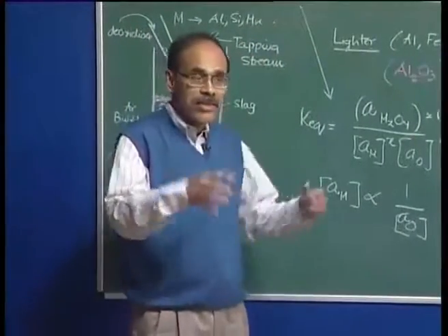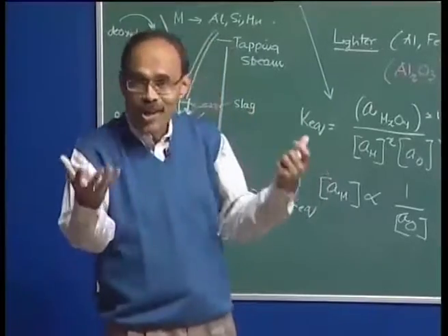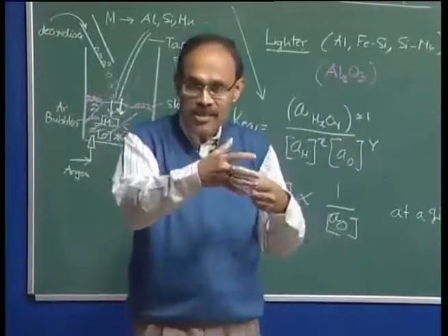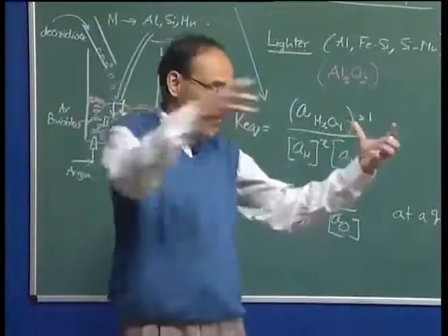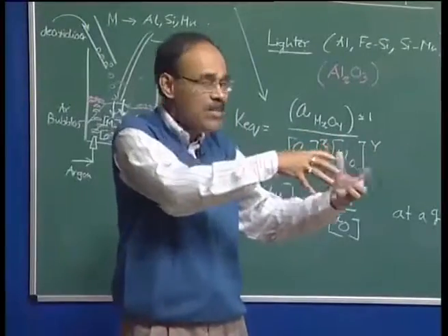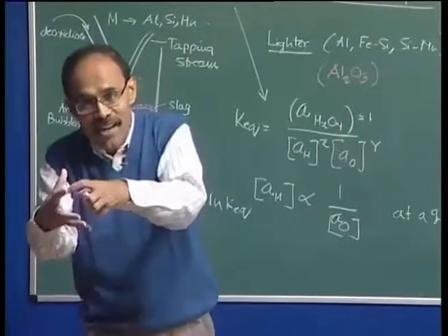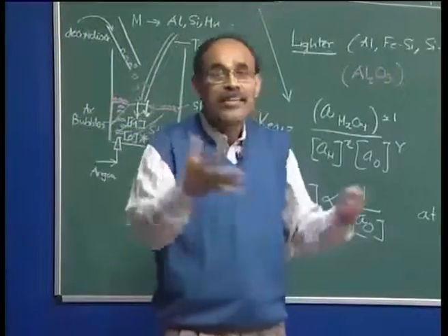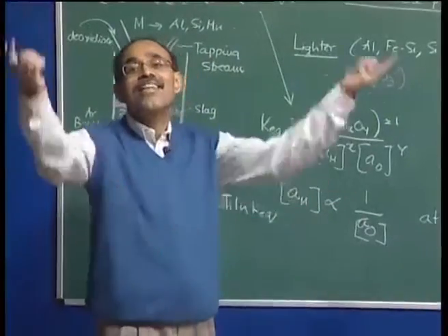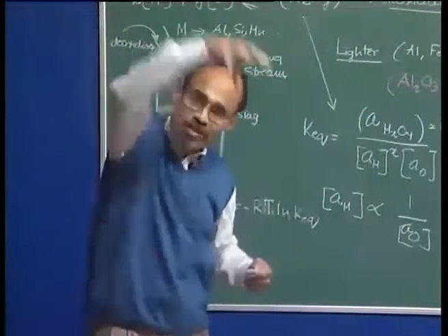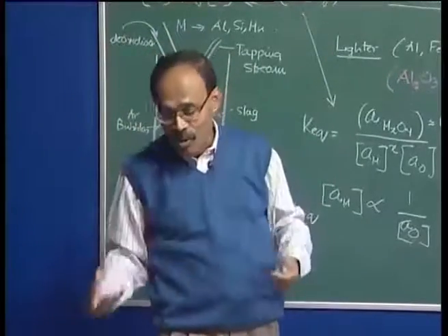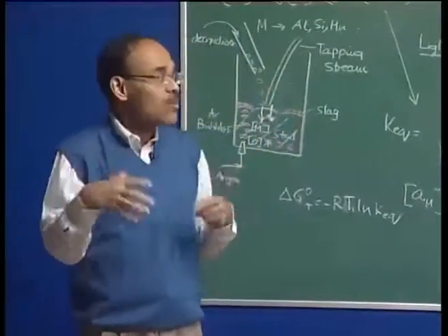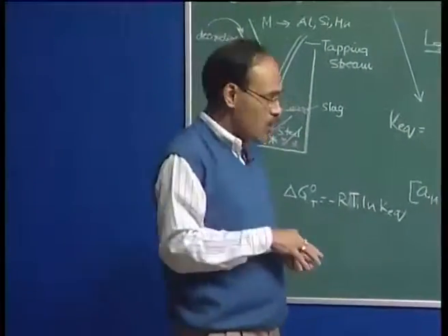Now, once the deoxidizer element gets into the bath, it melts and dissolves. Once it dissolves, it reacts with oxygen. So it is a mass transfer process, because oxygen has to find a dissolved deoxidizer element, and the dissolved deoxidizer element has to find an oxygen atom, and that is how they can collide and form a new phase. So this is the mass transport step, and therefore we need some kind of stirring. That stirring is initially provided by the convection generated by the falling stream, or alternatively, when the intensity dies, we have gas injection, which is always being used, and that gas injection gives rise to stirring, which aids the deoxidation process itself.